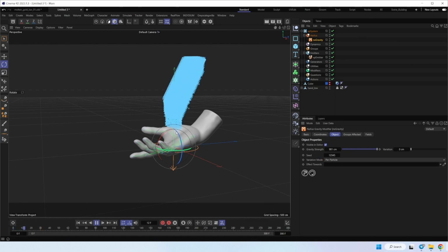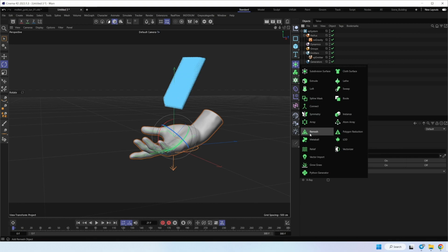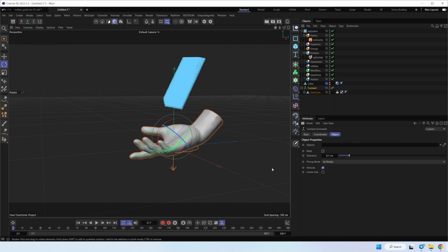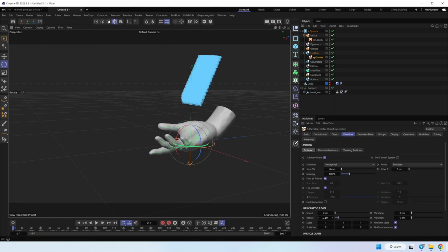For example, the first one is our particles going through all the geometry. So first, we place the head into connect object and turn off weld. Also, as you can see, it's going pretty slow because we have too many particles for now. To make a test, we don't need a lot of particles, so we can change size to 3. And let's check it again.